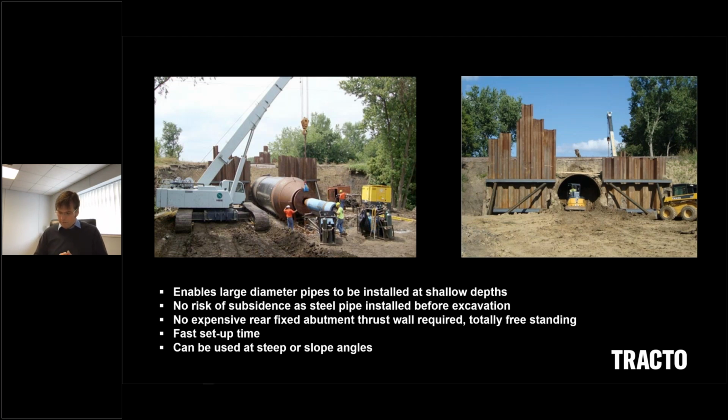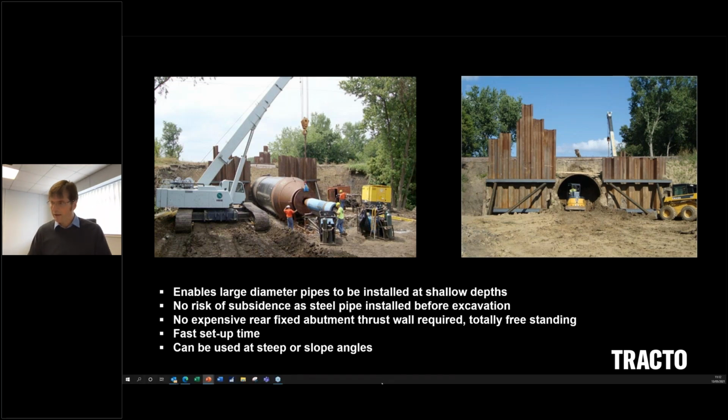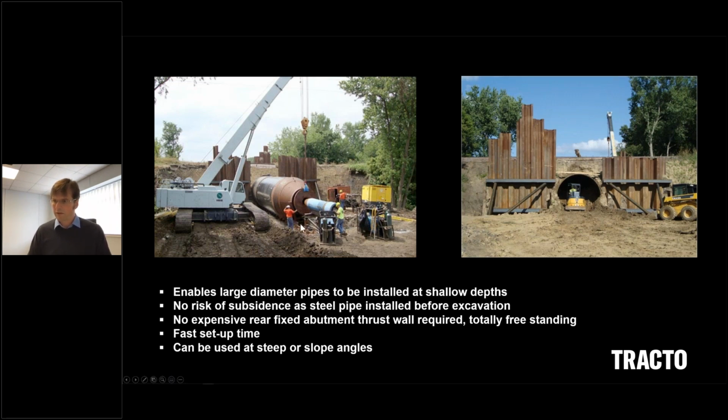There is no need for big abutments or thrust walls, no extensive civil engineering around it, other than the excavation of the starting and the receiving pit, and maybe the installation of any guiding rails that you can see on this first picture here. So one of the advantages is a quick setup and also a quick demobilization after the job has been completed.